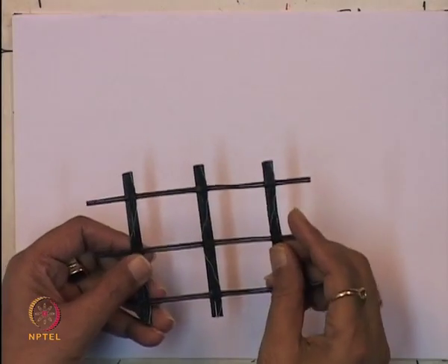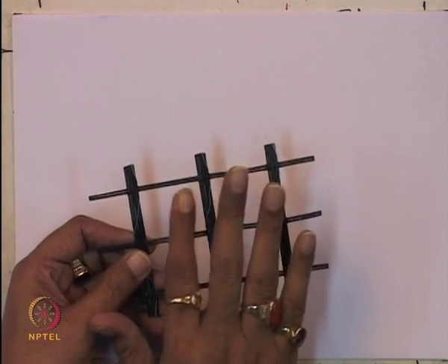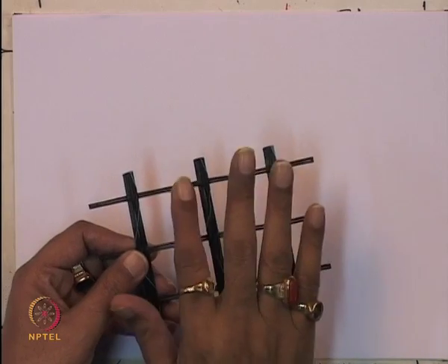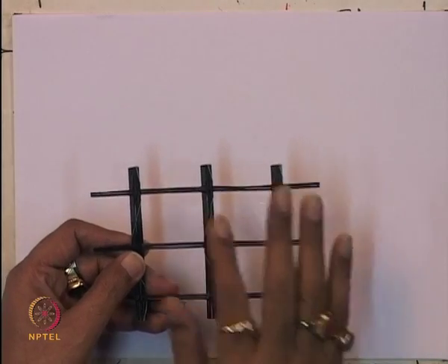Now the second part is the passive resistance. For example, this is a geogrid material. You can see that if you pull it out, there will be a development of frictional resistance as well as passive resistance here. So I am just showing how this development occurs, the frictional resistance and passive resistance.